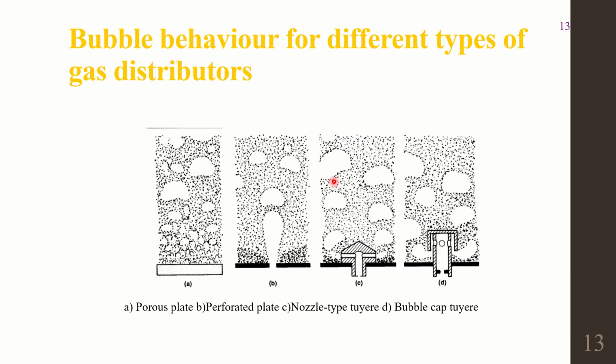I think that's all. Here we can see so many bubble formations, single orifice. Here the velocity would be UMF. Here the velocity would be UOR. Orifice velocity would be high. In other regions, minimum fluidized condition would be maintained in these zones. And these are perforated plates.